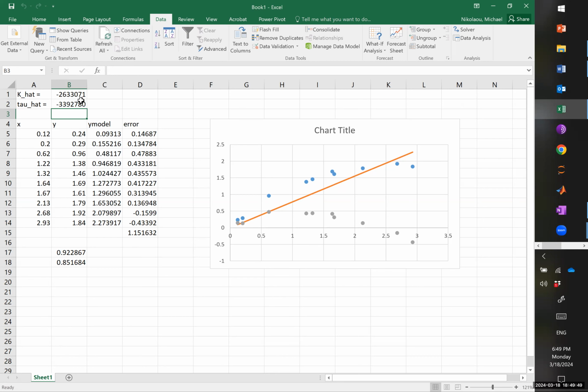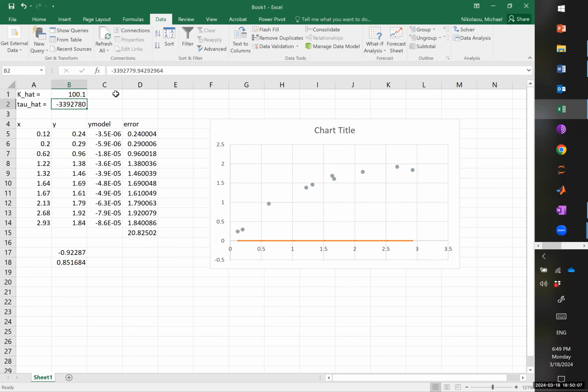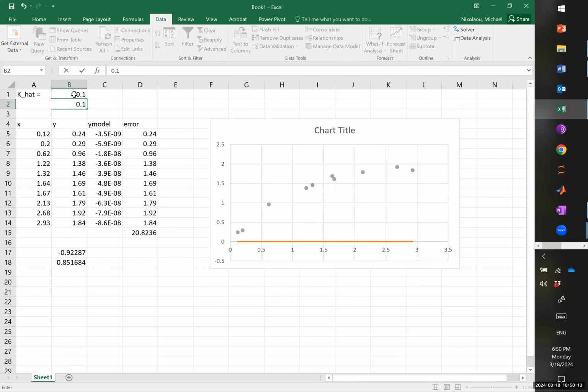It's not that it doesn't fail. The thing though is that in most problems of this nature that you solve, you say, what the heck, this is a positive thing because I made a change in my input and the output went up. So the steady state again must be positive. So I'll choose a small number, let's say 0.1, not 100. And the time constant, well, that's another positive number. So I would choose my initial guess like this.